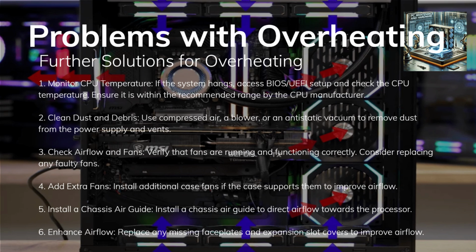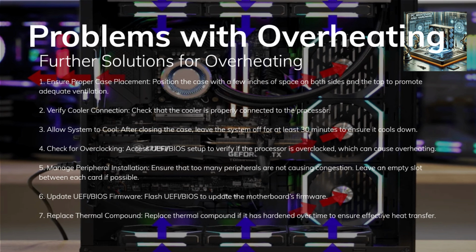If the system is overheating, use compressed air, a blower, or an anti-static vacuum to clear dust from the power supply and vents. Ensure that all fans are running properly; if not, they may need replacement. You can also install extra fans if your case has room. To improve airflow, consider adding a chassis air guide to direct air toward the processor, and replace any missing faceplates or expansion slot covers. To further address overheating, ensure there are a few inches of space on both sides and the top of the case for proper airflow.